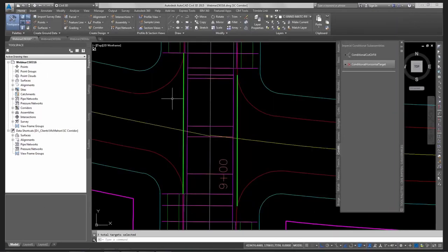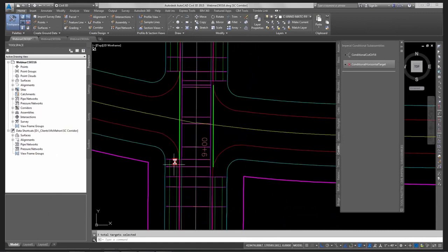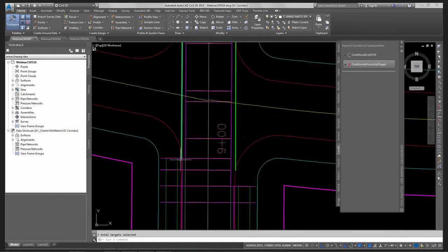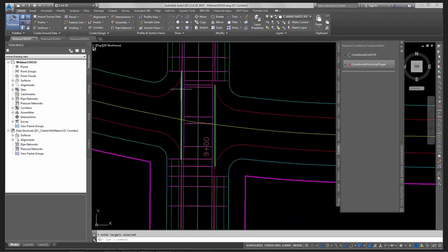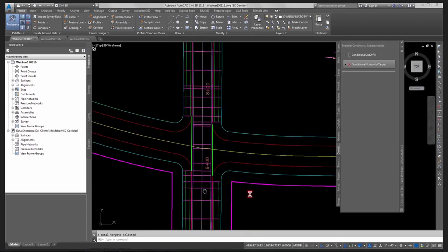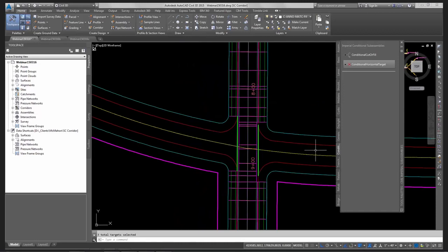Rebuild. And that quickly, it found my polyline and it dropped everything outside of the edge of travelway where that polyline existed. So now I have my through intersection, and now I can build my other corridor running east-west, and I can then tie into this corridor here.